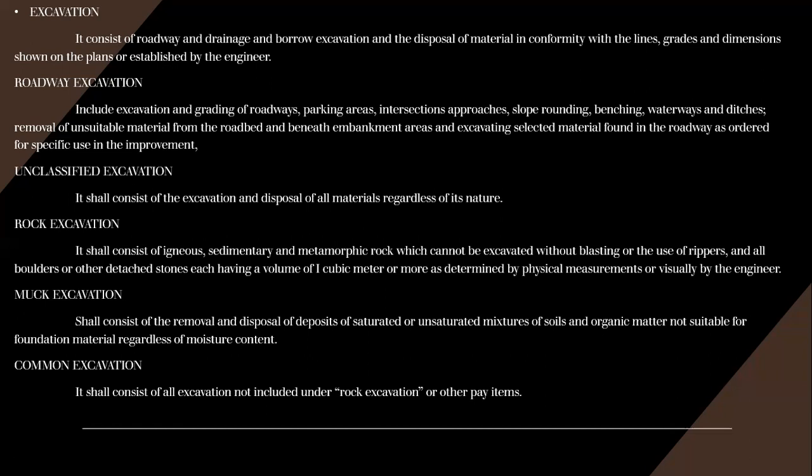Rock excavation shall consist of igneous, sedimentary, and metamorphic rock which cannot be excavated without blasting or the use of rippers, and all boulders and other detached stones, each having a volume of one cubic meter or more as determined by physical measurements or visually by the engineer. So we understand rock excavation, which is removing rocks.